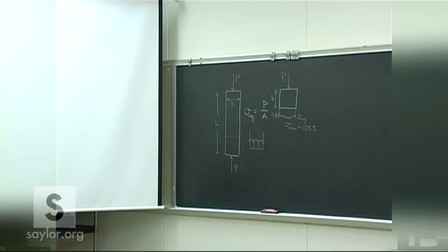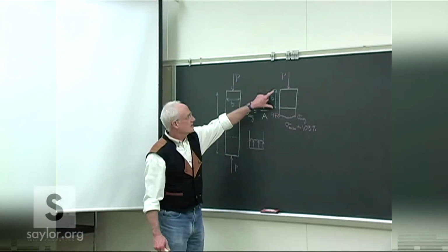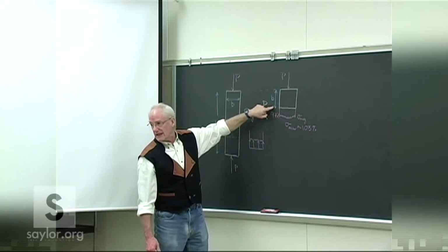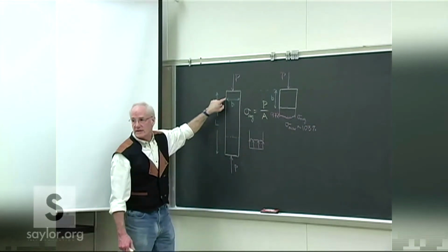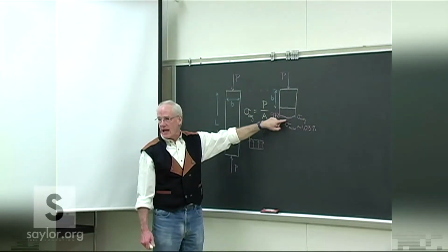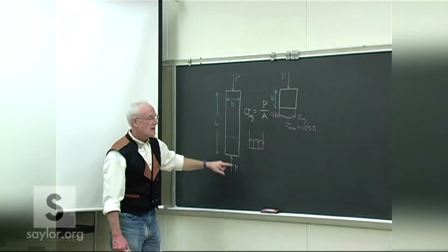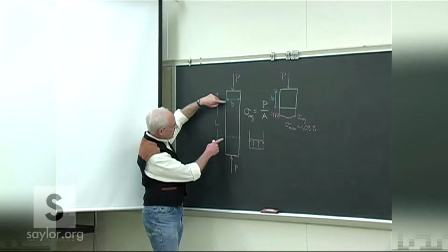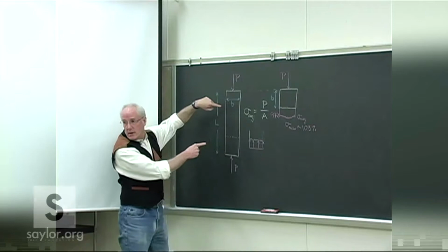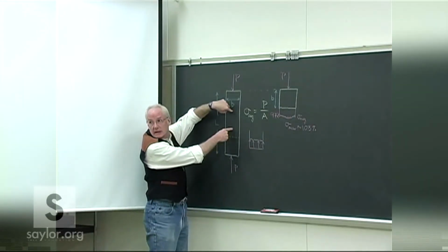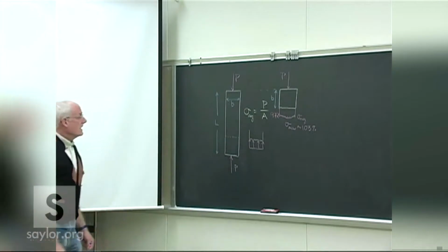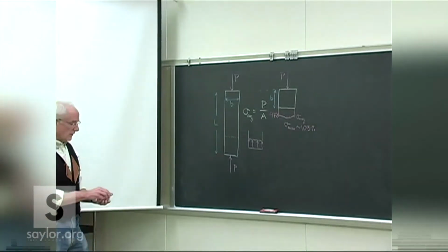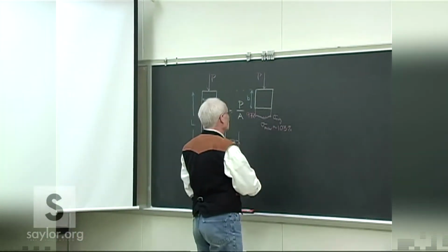Why don't you go like 8, so it's perfect? No, not so it's perfect, just it's very easy to remember that once you get about a length into the piece that's equivalent to about the depth, then you essentially have a uniform profile from then on through the piece. Until you get down to the other end when it starts reversing. So that leaves a huge majority of the piece. And if you remember, all of the test sections were always in the middle here. If you have a very long piece compared to its width, it's essentially under uniform stress everywhere, and we don't have to concern ourselves with it too much.